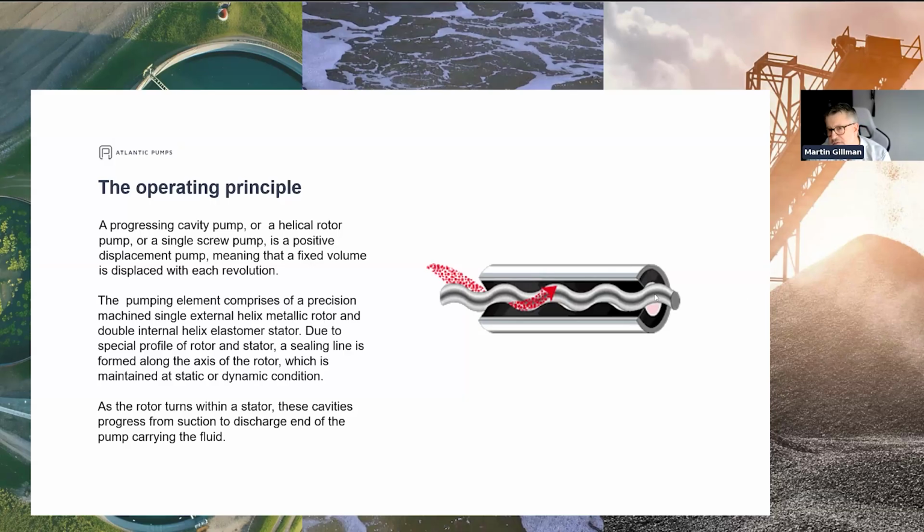And because we have an interference fit between these two elements, as we push our liquid forward into our vessel, which is normally pipe work, which is of course restricted, then we will begin to build pressure. And the curve, although it's a bit of a lie, so to speak, when we draw it for this kind of pump, the curve is actually a linear curve.